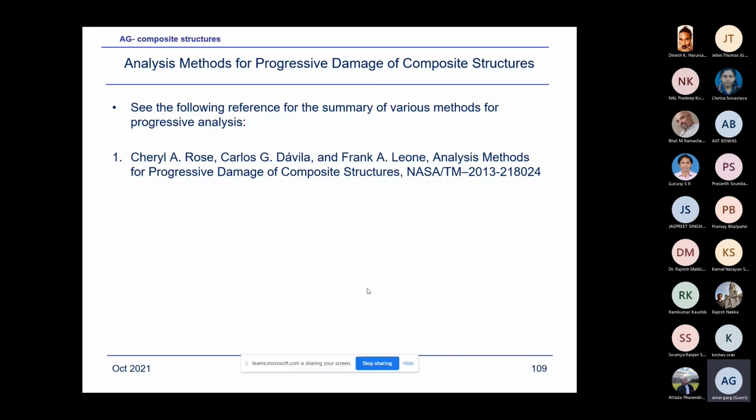But everywhere you have to analyze for large damage requirements, like a discrete source damage. You cannot build a finite element model that sophisticated because it will consume too much memory, runtime and CPU time when you are trying to analyze these damage problems.